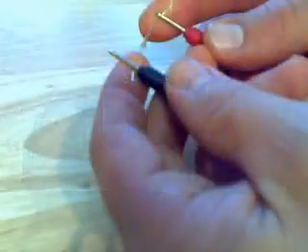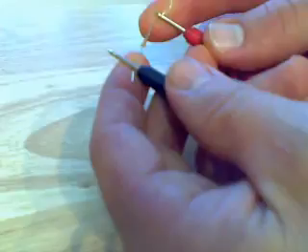When you touch the meter probes to the resistor terminals, try not to touch both probe tips with your fingers. If you do, you will be measuring the parallel combination of the resistor and your own body, which will tend to make the meter indication lower than it should be. When measuring a 10K ohm resistor, this error will be minimal, but it will be more severe when measuring higher values of resistor. How does touching both probes affect the 100K ohm measurement?